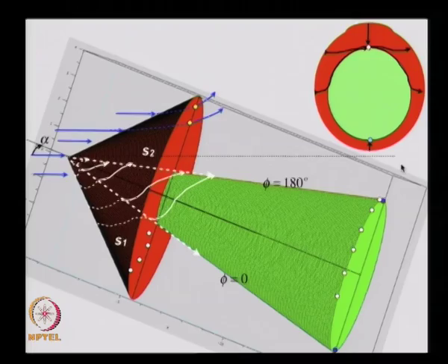So the streamlines which are generating from the bottom or the windward side of the cone and moving up on the surface of the cone are encountering an entropy S1. So all these streamlines that you see have an entropy S1, an entropy change of S1 as they go here. And these streamlines go ahead and converge on the top.